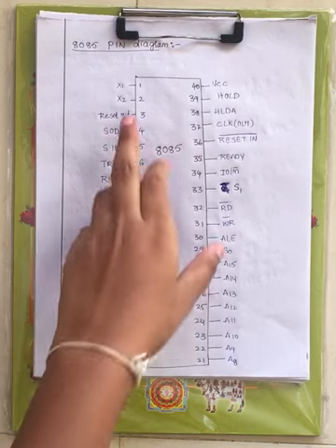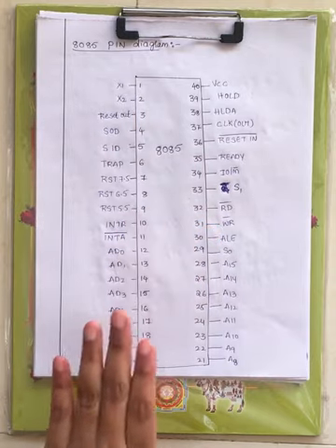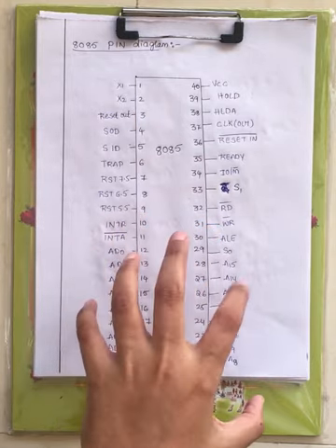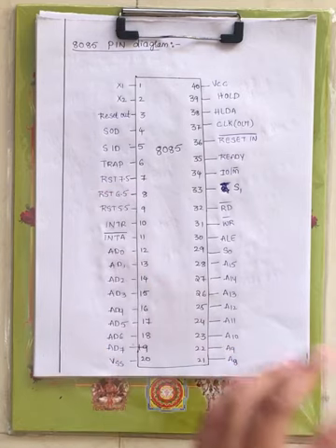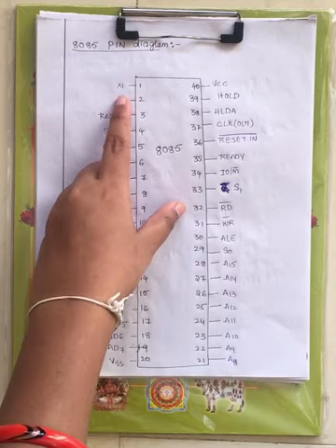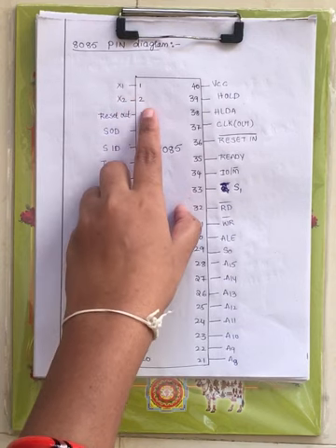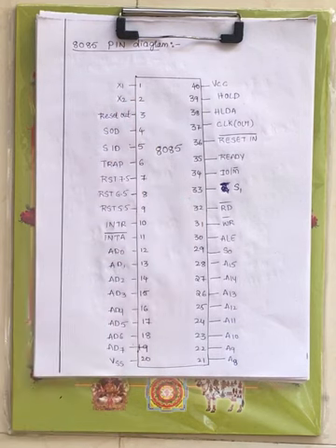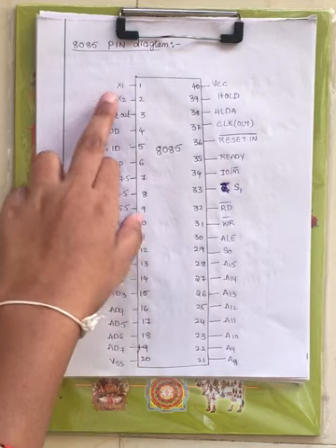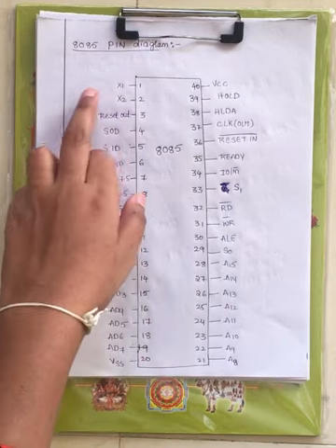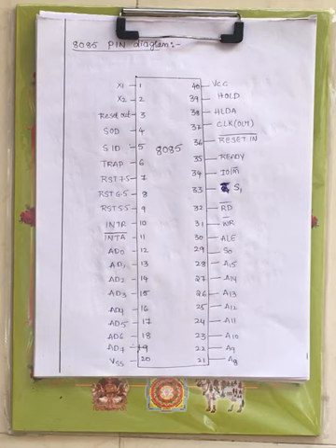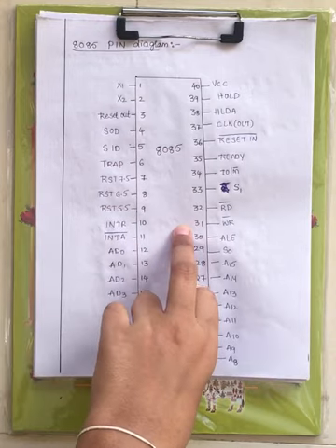First, I will briefly explain what is meant by these particular pins. Later we will see their operation. Pin 1 and pin 2 contain X1 and X2. Here we will connect some circuit to provide the clock signal to the processor.